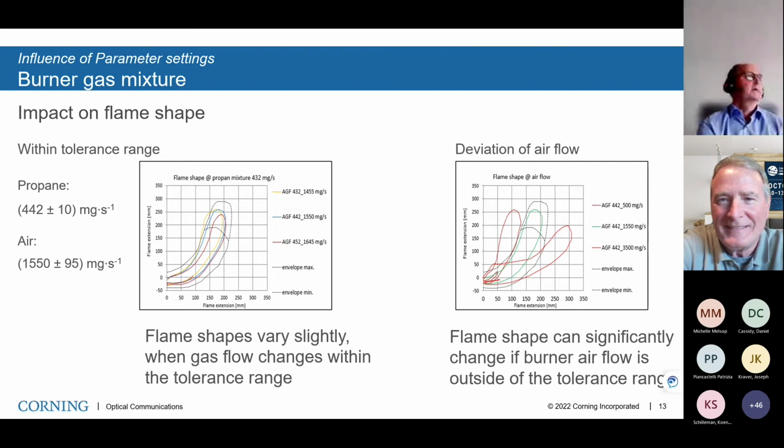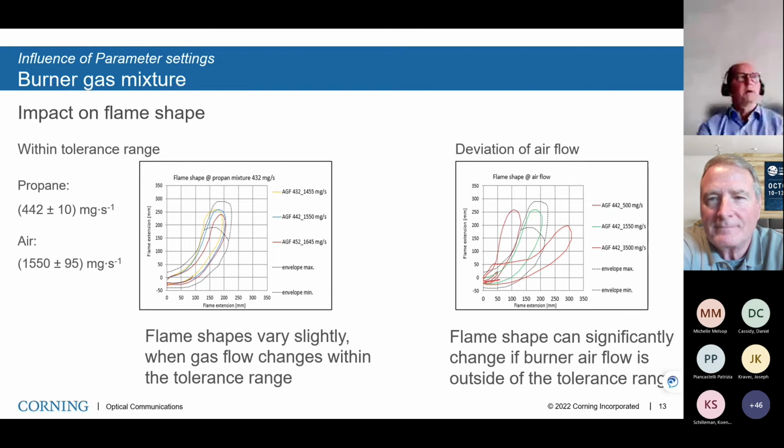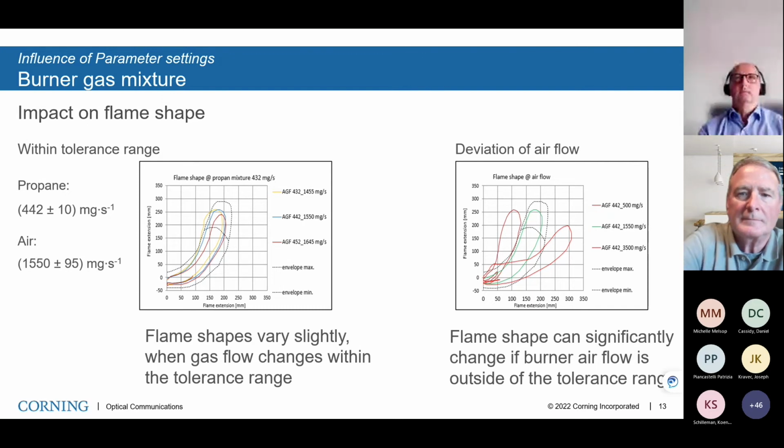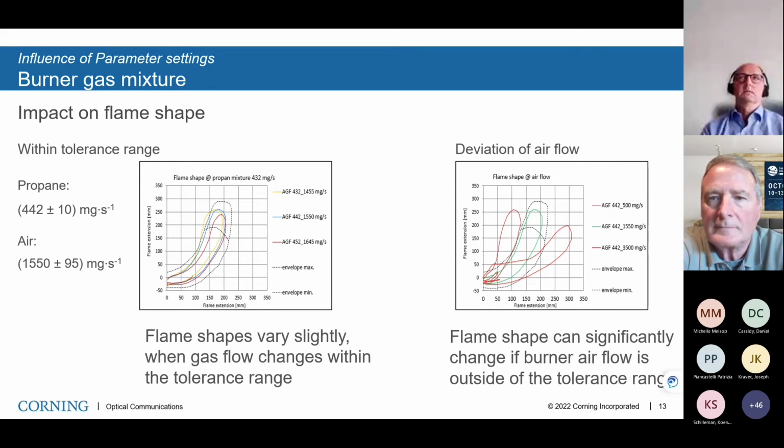One key parameter is related to the airflow through the chamber, and there are a number of parameters which can affect the overall airflow and air distribution in a chamber, like the air which is fed to the chamber, the extraction air, chamber build inside, leakage and so on. There are a number of parameters which can also impact the flame spread results, finally the burn test results.